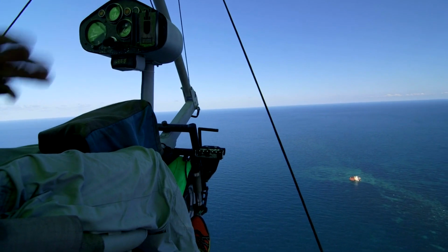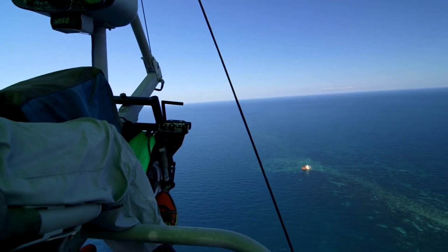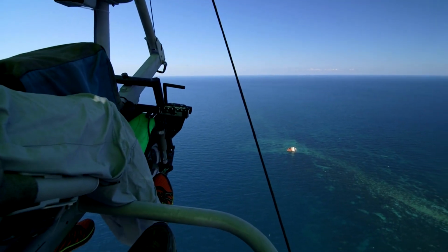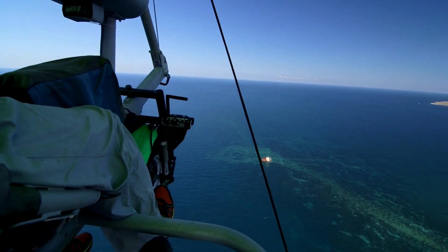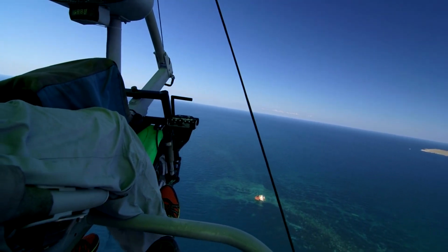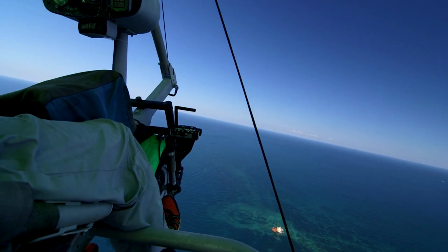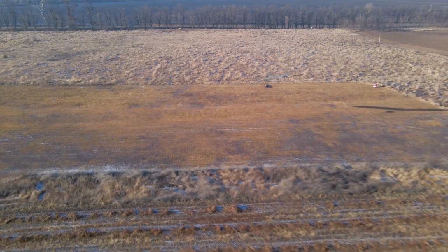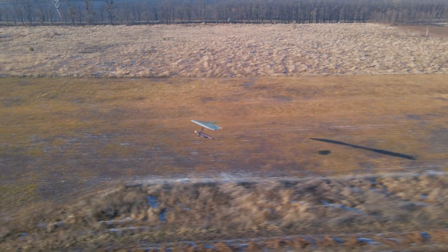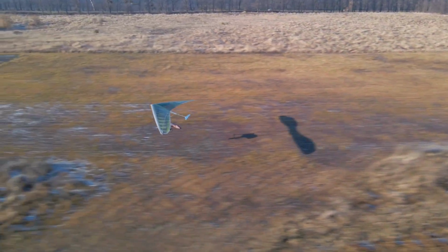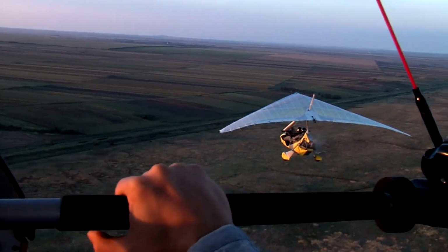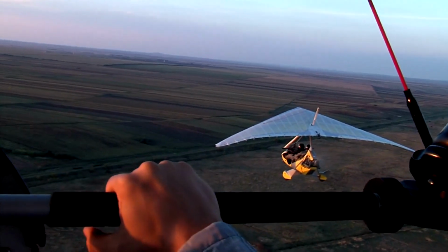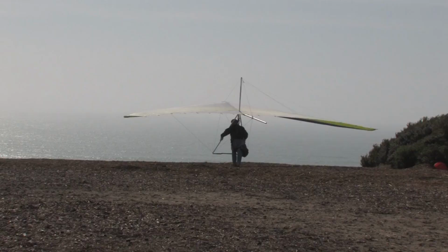The design of a WSC aircraft involves a trade-off, considering whether it is intended to be a slow-flying aircraft with a large wing, where drag is less critical, or a fast-flying one with a small wing, where drag becomes a more significant concern. Total drag, a combination of parasite and induced drag, is essential for understanding overall aerodynamic performance. Total drag increases with slow airspeeds at high angles of attack, reaches a minimum at the most efficient airspeed, and then rises as speed increases.